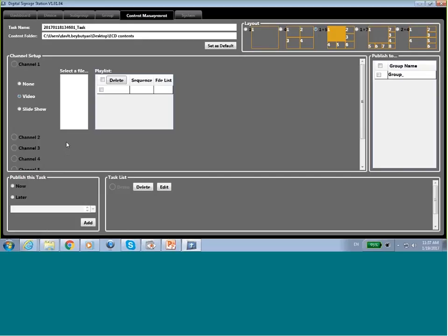You configure the layout, even while the digital signage is working. You can remove the PC anytime, and if you remove the USB drive, you will only be able to see your cameras. If you plug the USB drive back in, you can see that the contents are there already. Oh, so you need to have the USB inserted. The USB drive should always be inserted in the ECD1000 for using the digital signage content. And I would also like to say that the USB drive size should not exceed 128 GB. This is the maximum size limitation we have for the decoder.